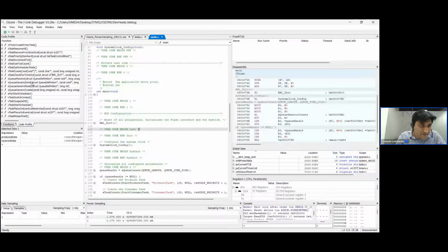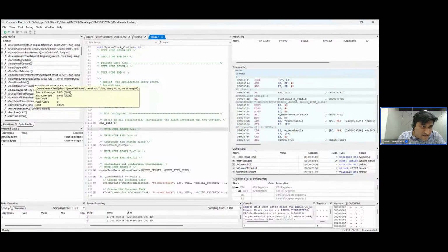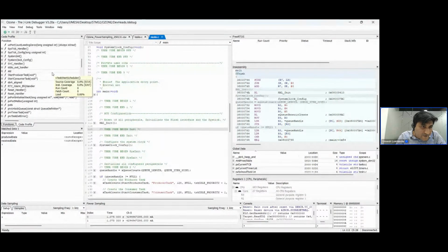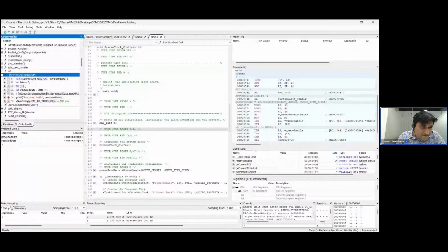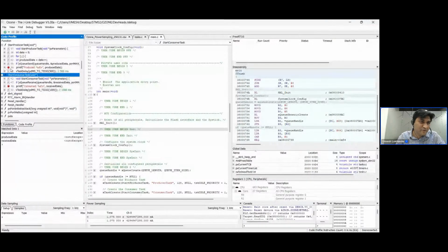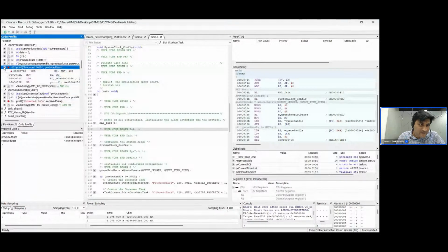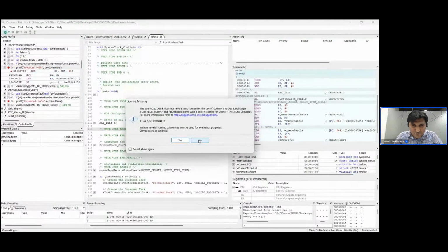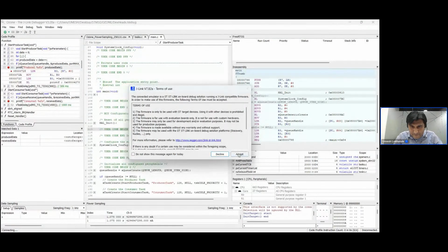In the code profile, you in fact are able to see the task that we have created. I hope I will find it pretty quickly. Look at this. I can expand and I can see every bit of a thing, even the breakpoint in this. You can even expand this and you can see the assembly instruction in it.